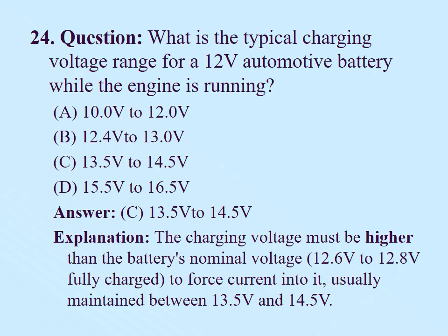The charging voltage must be higher than the battery's normal voltage, that is 12.6 volt to 12.8 volt fully charged, to force current into it. Usually it is maintained between 13.5 volt and 14.5 volt.